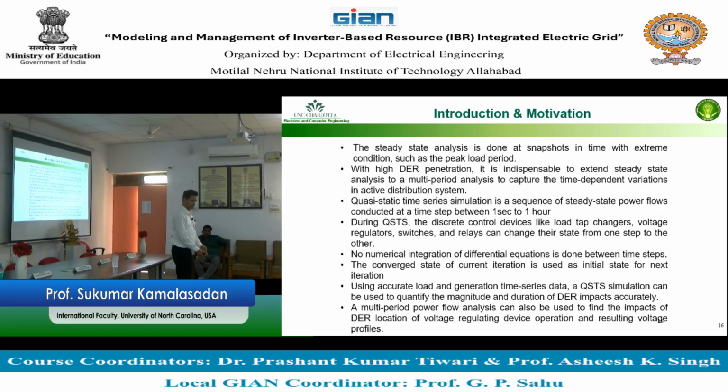Then, so I told you the steps. Power flow: multiple power flows done in a year. Time series power flow: which includes the changes of the discrete devices on the power system, for example, voltage changes in the voltage regulator. So, no numerical integration, no differential equation. Okay, it is just the changes on the discrete time step.